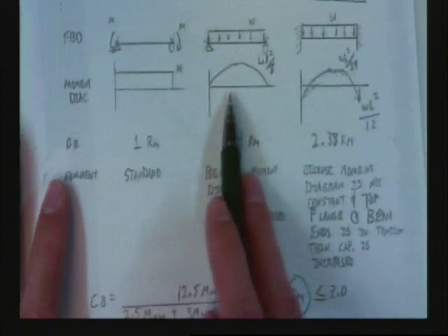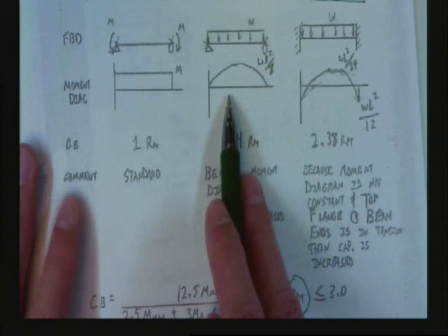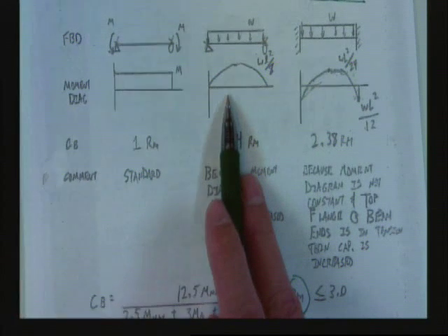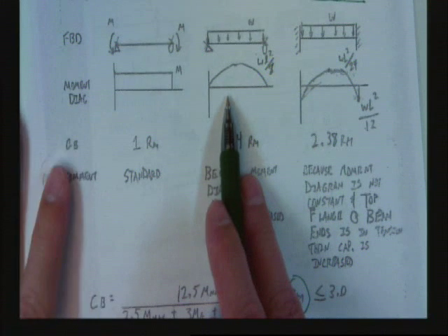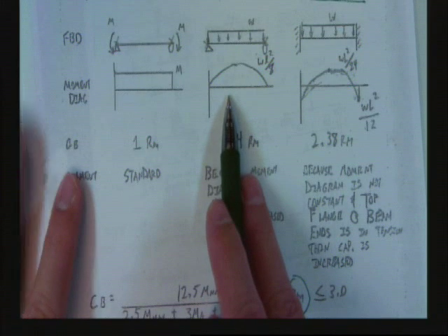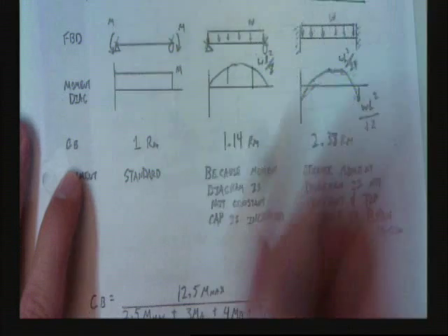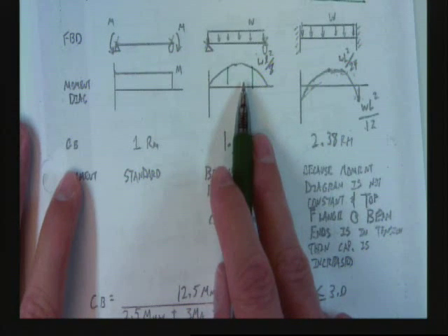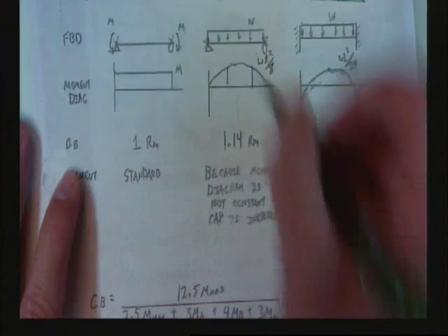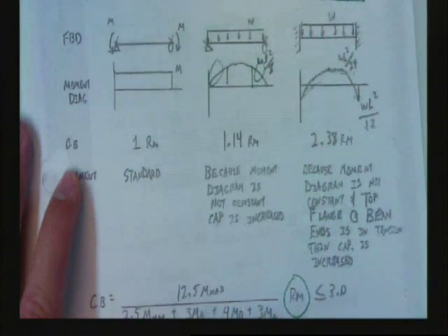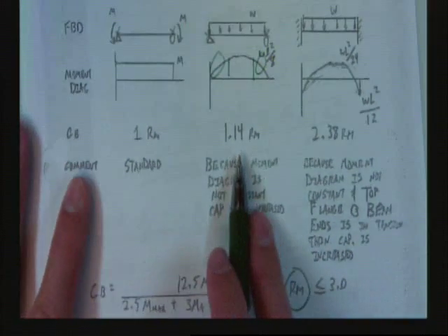The moment diagram is not constant. What value should we get? Greater than 1. Good answer. And now it depends on how non-flat it is. We could say that the majority of this moment diagram is still pretty flat, with non-flat out here. We get about a 14% increase in strength.